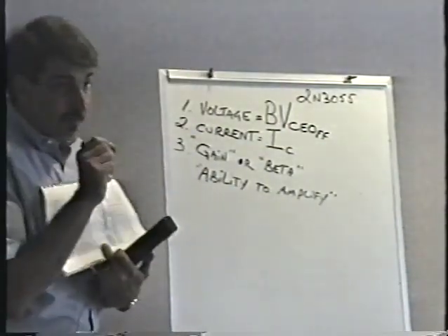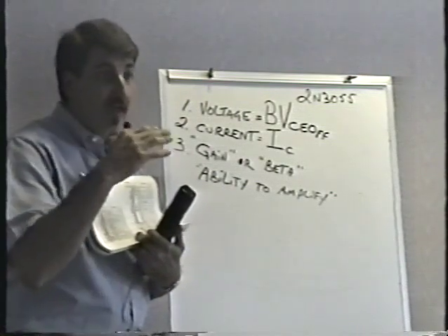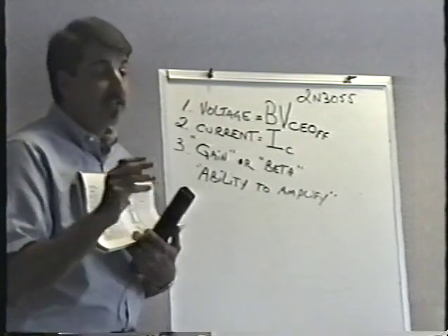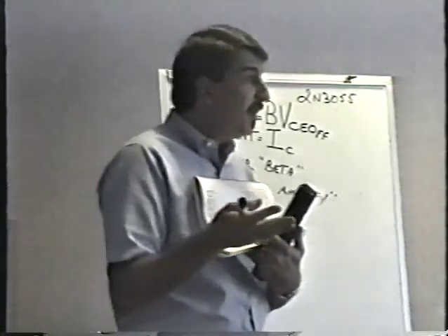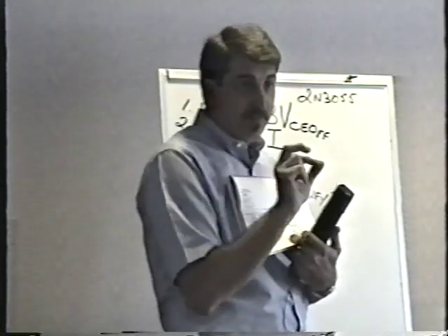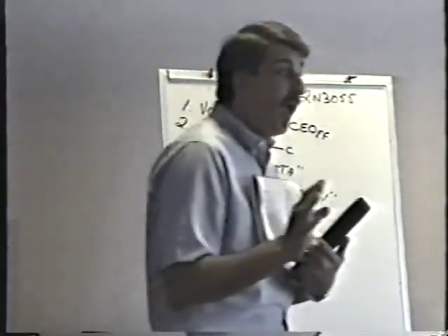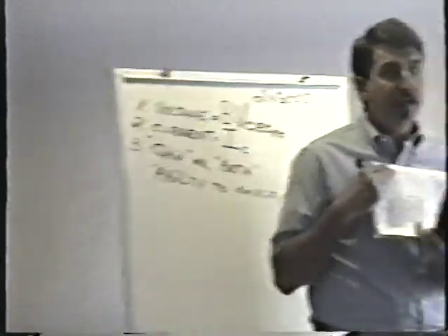This is the same part with the same specifications, same voltage, current, and all that stuff, but opposite polarity. It's PNP instead of NPN. It's called a complementary pair. You don't really have to know that, but two transistors with the exact same specifications, but opposite polarities, are not interchangeable in any way. You can never interchange an NPN for a PNP under any circumstances, no way, no how, nowhere.